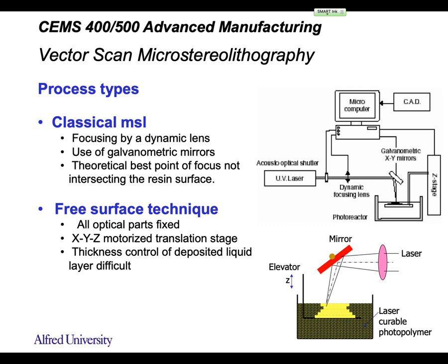Usually you have this mechanical linear rail to control the z-axis, and that resolution is usually limited to around 50 microns, right? So if you have a thinner cure depth, if you have a cure depth less than 50 microns, you have to modify this z-axis, right? So you need to calculate this cure depth to make sure you can work with that. There's a need to modify this z-axis.